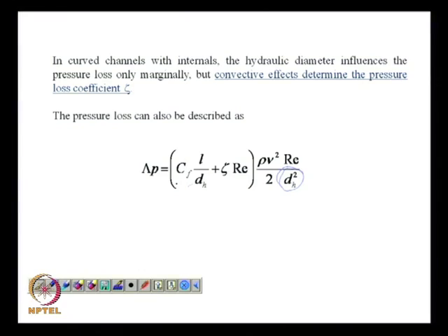Okay. So, electric field is one example, but that would give rise to interesting effects such as electrokinetic effects. What happens to the viscosity when you use an electric field to move a liquid from one side to the other? Because the electric field near the liquid-solid interface would create ordered structure in the liquid molecules. So, the apparent viscosity of the liquid will be much more than the actual viscosity of the liquid.